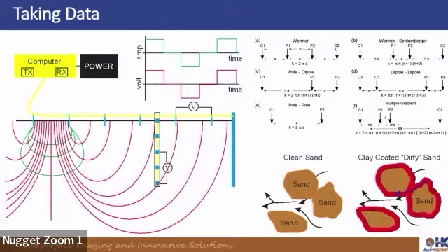We pass electrical current and then measure. The current is in the blue lines, and that sets up an electric field, which is the red lines. So then we measure the voltage, which is just the difference in the potential field. We put current in the ground, something that looks like this: positive polarity, negative polarity. And our voltage that we measure with our receiver has a similar shape. And then there are different arrangements of how we can put our electrodes in the ground, put a current in the ground, and measure our voltage.